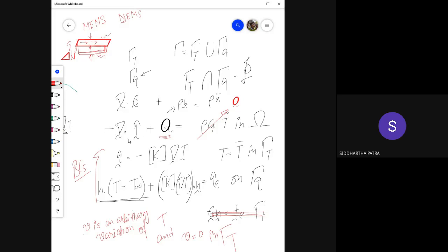would result into what? Thermal elongation, which is associated with another coefficient which is called coefficient of thermal elongation. Okay, and with that you will see more deformation on this side, on the thinner side compared to the thicker side, and eventually the structure bends like this. This tiny structure bends like this and acts as an actuator. Okay, so it can switch on or switch off a system like this.